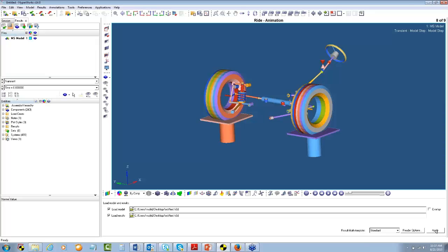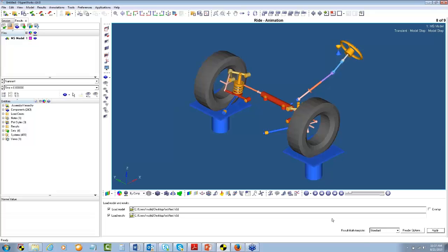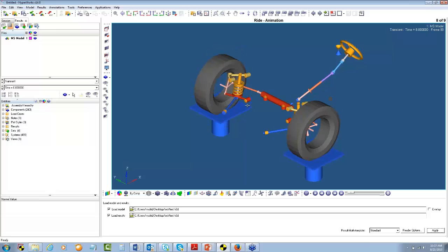So this was the event which we were doing. You can see that this is a bad suspension. It is gaining a lot of toe when it goes down, which we call bump steer, and that is very undesirable. Why is that?